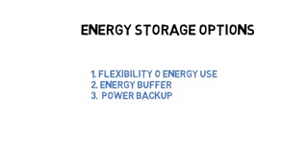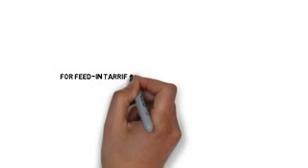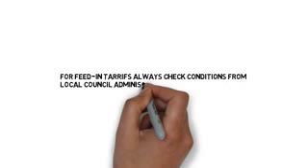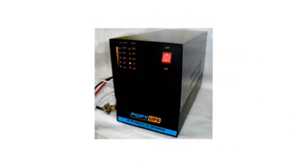Now, it should be noted that if PV installation is being done to make use of feed-in tariffs, then it must be checked beforehand with the utilities or the electricity supplier whether they allow systems with battery storage or not. In many countries, low-cost UPS systems are available and are made by the local cottage industry.